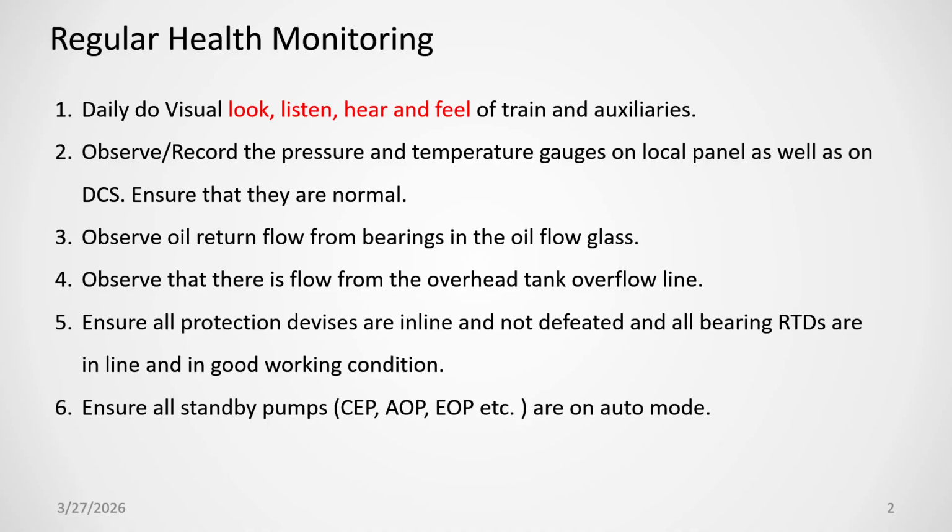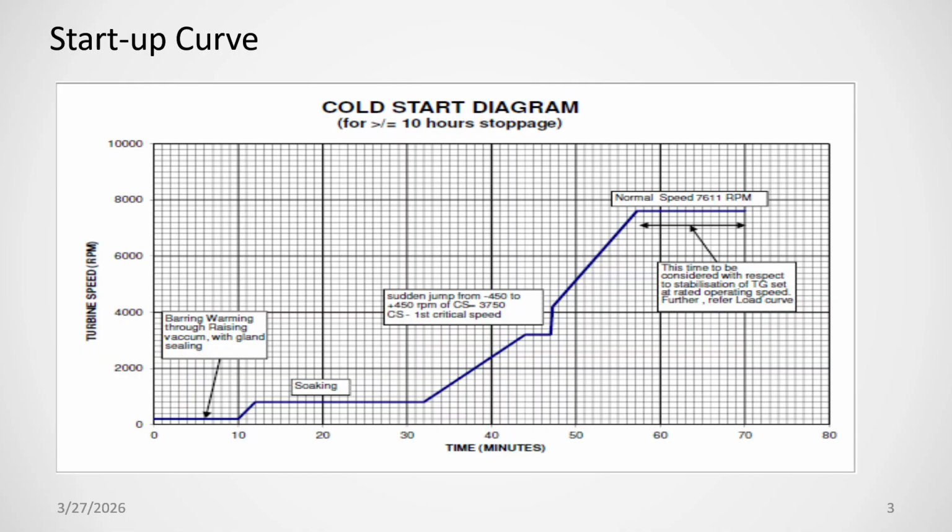All the protections should be in line, not defective. All bearing RTDs are in good condition, and ensure that all the standby pumps like the condenser pump, AOP, UOP are in auto mode. If any one is not working, the standby one automatically comes in line.